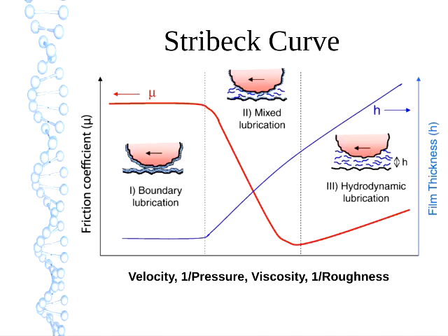They're entirely separated by the lubricant film, and what we see is that as you move further to the right, it takes more effort, more force, or stress, to shear that lubricant film separating the surfaces, and that is what's causing the friction to start rising again. We aren't seeing a reduction in friction from fewer asperity contacts, which is what was happening in mixed lubrication, because there's no more asperity contacts to be removed.